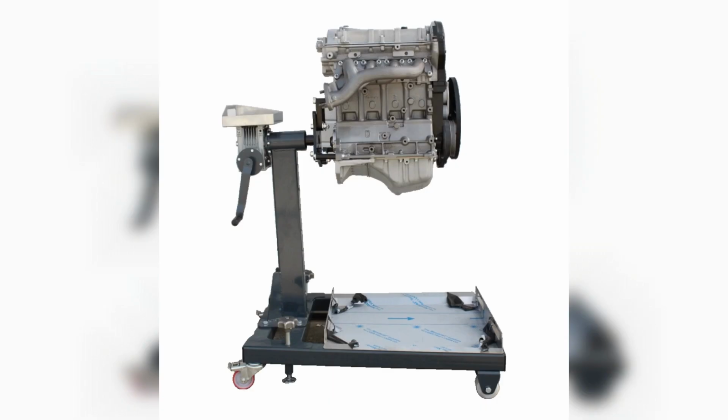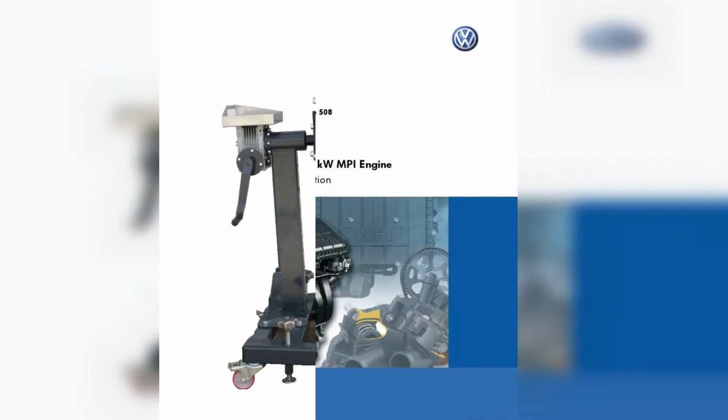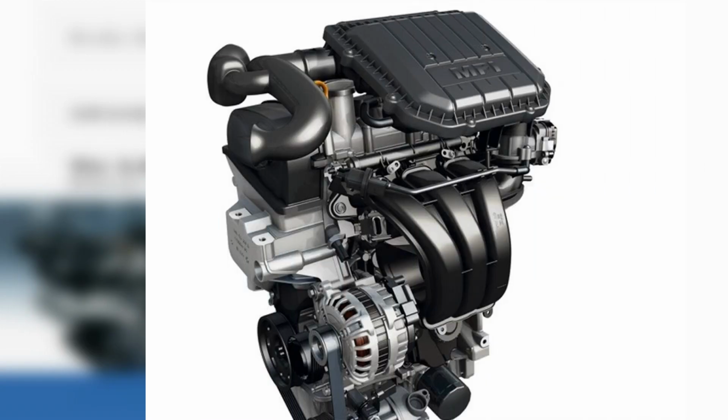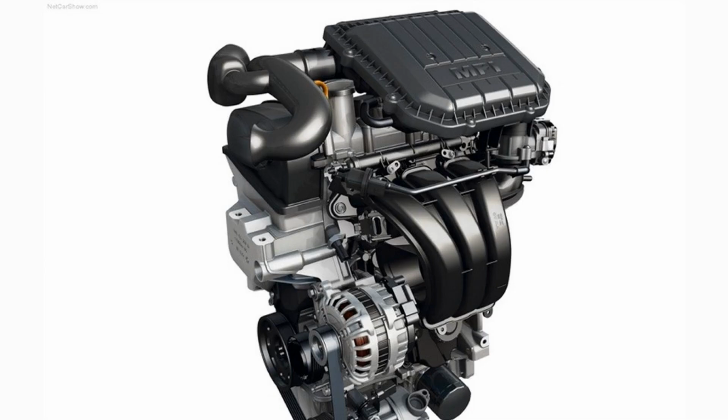Reduction of gasoline evaporation losses. The injectors are located in close proximity to the intake valves, so there is no need for significant over-enrichment when the engine warms up. The location of injectors close to the valves allows gasoline to remain in the liquid phase longer after injection, which reduces the temperature in the combustion chamber. Any increase in detonation resistance allows the compression ratio to be changed and engine power to be increased. Higher injection pressure allows the fuel to be broken down at the injection stage into finer particles, thus improving its ability to vaporize and mix with the oxidizer.